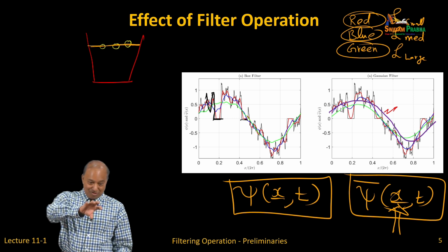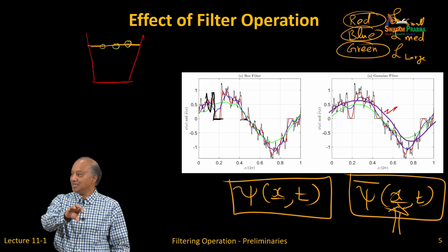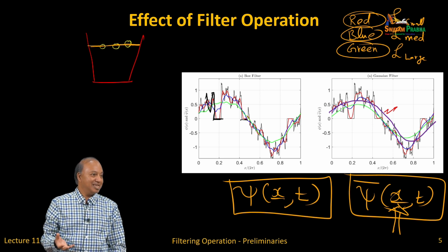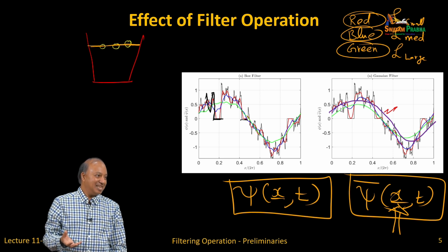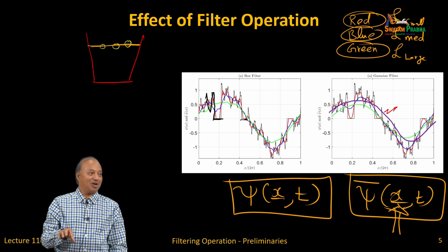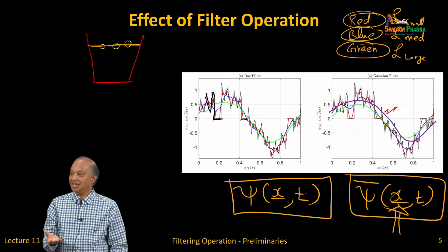And you are not resolving the flow. So you have a point particle which is as big as your grid size. It starts making less and less sense, and you are going to use a drag law which is good only on an average sense. Like yesterday we talked at length about it.